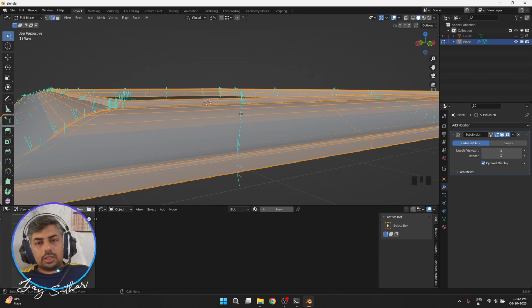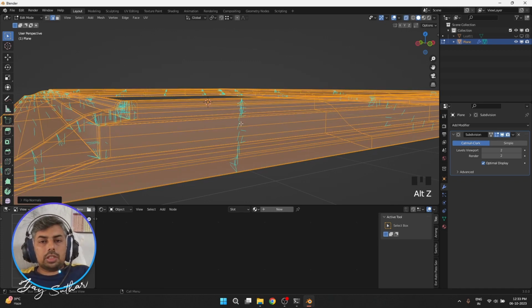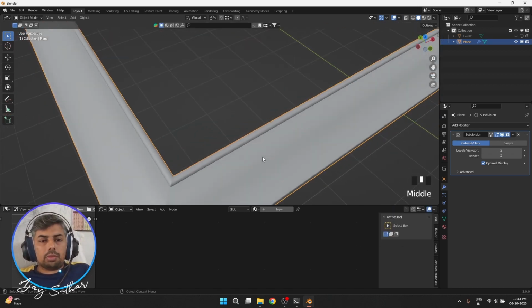How the normals are correct or not, you have to understand by checking the normals. The blue hairs, these lines, are placed perpendicularly on each face. The direction of this line explains whether this is a good side or bad side. If this is on the inside or opposite side to us, where we cannot see clearly these edges, then we have to flip it out, like Alt N, flip. If everything is directing towards inside, then that's wrong. Alt N and flip. Here we can see, so this is the correct one. So switch off these normals. Now come out from edit, and here is the frame.